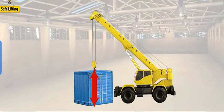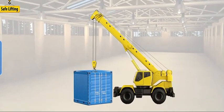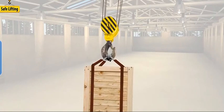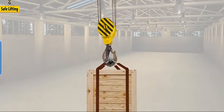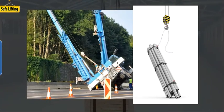Also avoid shock loading, a term used for sudden stops and starts. For example, if you picked up a load very fast and stopped the hoist, the load's momentum would continue to carry it up for a second or two, then the load would drop, putting pressure back on the cable and possibly causing it to snap, or in the case of mobile cranes, causing it to tip over.